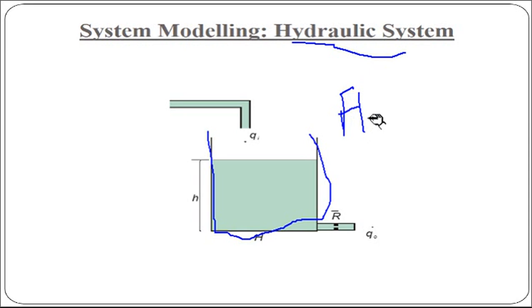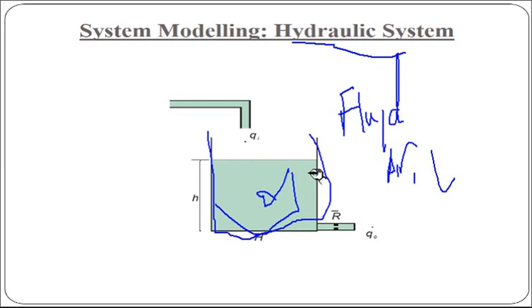Again, as we applied the Laplace transform to the mechanical system, similarly we apply it to this thermal system. By applying the Laplace transform, we get the transfer function, that is output upon input, and we convert this into the thermal system model. That's what we have studied here.